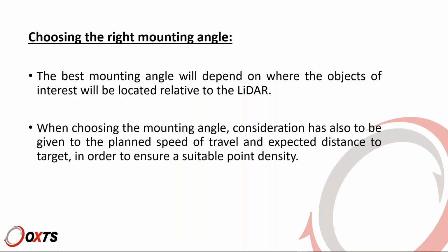So there is no fixed rule. It will depend on where the objects of interest are. You know, is it the road surface? Is it objects that will be on the side, and so on? And also, it will depend on the shape. Are they large objects? Are they very thin objects? What you want to do is to maximize the amount of time the target will be exposed to the LiDAR.